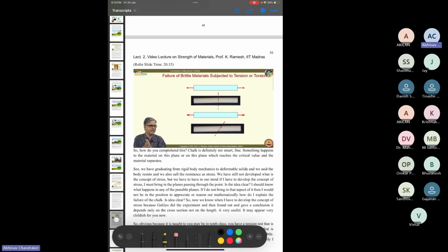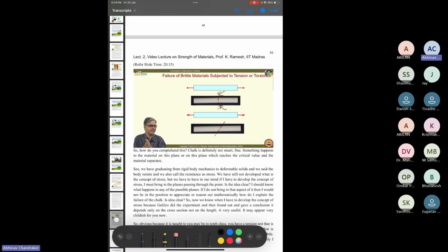thing related to brittle and ductile materials is that depending on how the material is, when you load it, the nature of the failure you will observe will be very different. In case of brittle material, you are more likely to have a kind of failure which is perpendicular to your loading direction, and it usually can be seen as forming a very sharp cleavage edge at the point of failure.